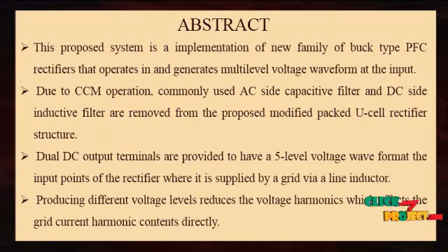Let us see about the abstract of our product. This proposed system is an implementation of a new family of buck type power factor correction rectifiers that operates in continuous conduction mode and generates a multi-level voltage waveform at the input. Due to continuous conduction mode operation, the commonly used AC side capacitive filter and DC side inductive filter are removed from the proposed modified buck rectifier structure.